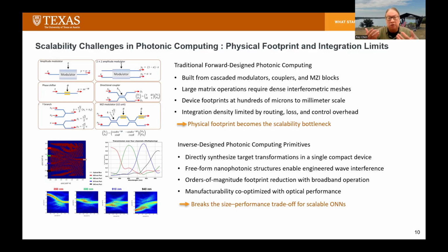So optical interconnects have taken off, but one thing they have in doubt is optical computing, because of the density issues. I think the inverse design we mentioned here is a very pivotal way to shrink the device size while enlarging the matrix multiplications with minimum power consumption. When you have a passive design, putting the modulation or the weights into the design phase, you don't need any energy consumption when you do the computation. So the idea is not only to save area, but also to save power.